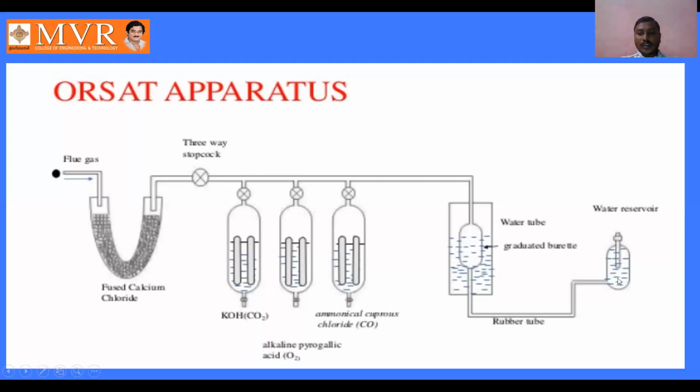When we give a pressure of water to this graduated burette, the gases are pushed and first enter into the ammoniacal cuprous chloride, where the gas is absorbed and the weight of the ammoniacal cuprous solution increases.